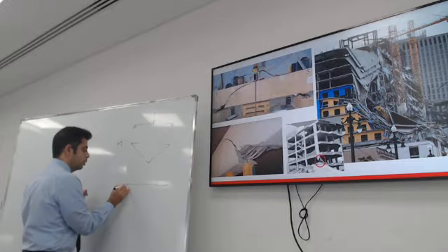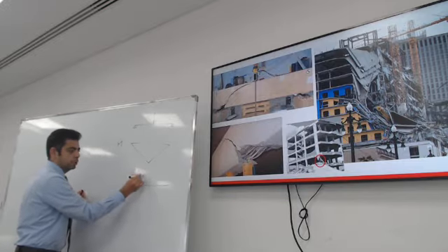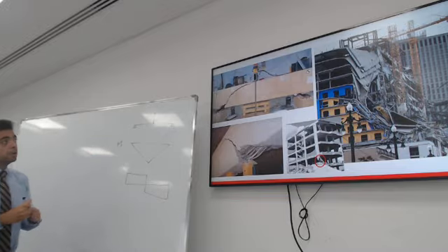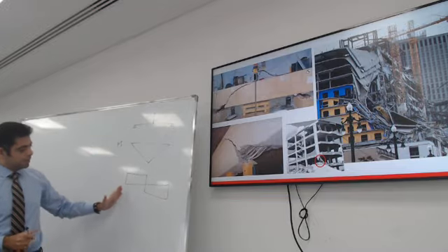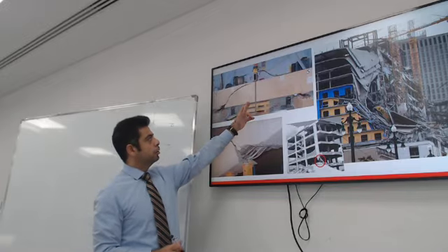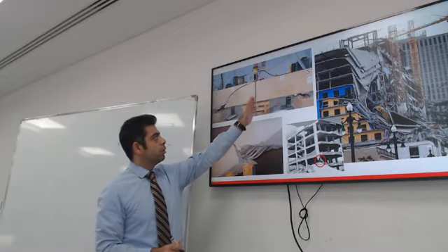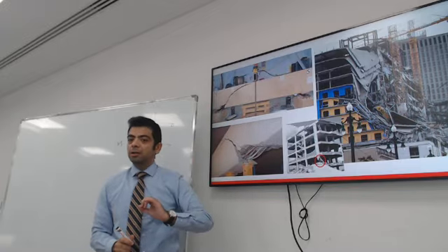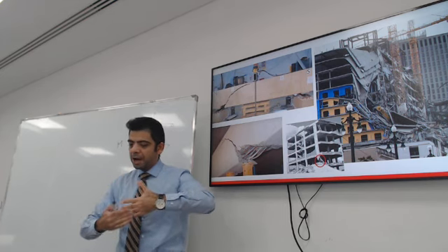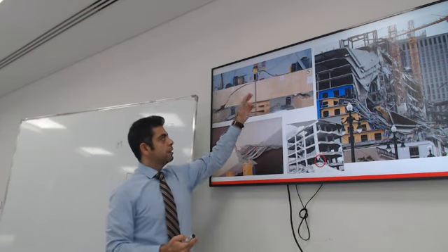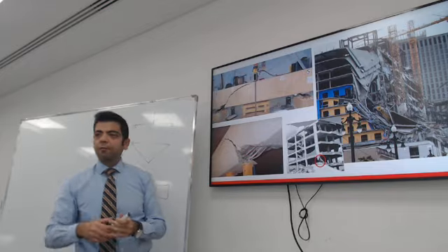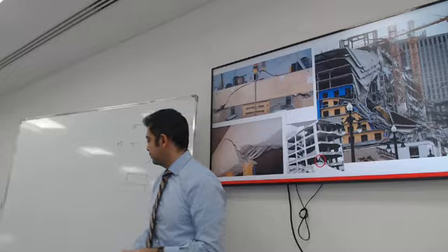The reaction will go constant, the point load will take it down, and then you will end with 0. So from the point load to the support, this whole part has a constant shear. The beam will start exhibiting some tensile cracks, which are vertical, but then very quickly will result in this 45-degree angle.